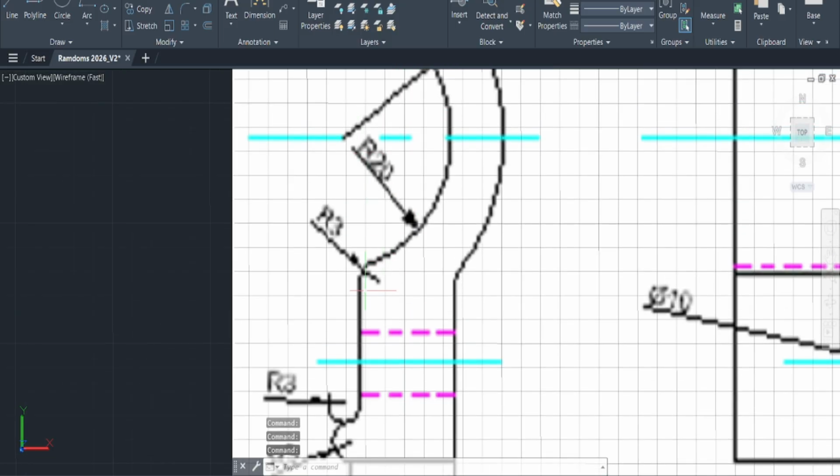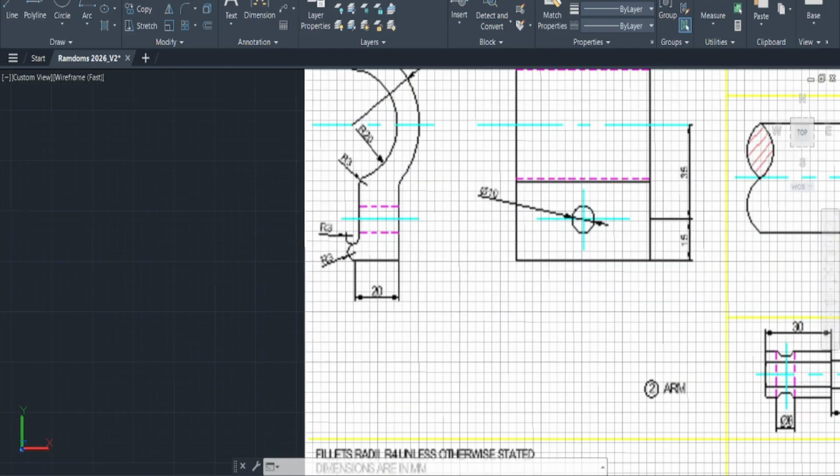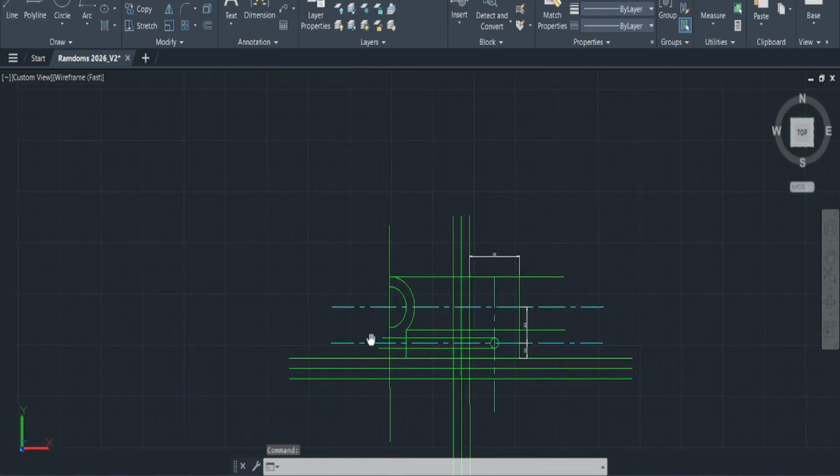Then we're gonna go all the way up, and then we're gonna have another curve starting here. And because this fillet-ish type curve comes on the edge of this, I can choose to do an arc at radius 23, meaning add the 2 radius just to get the center point of it, and then I could do another circle there and trim it accordingly. So let's see if we could breeze through that.